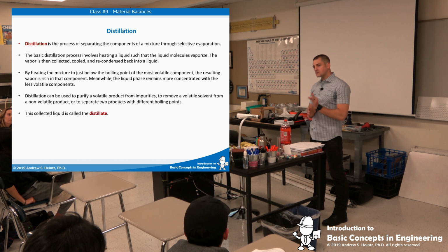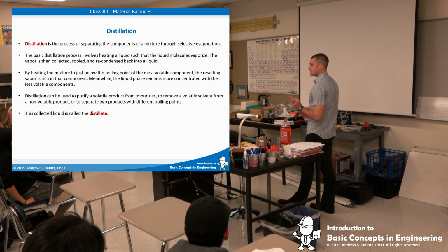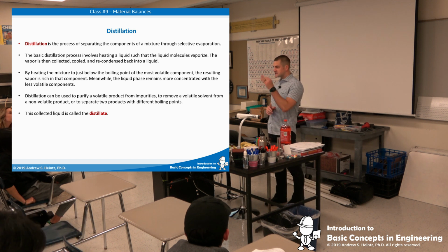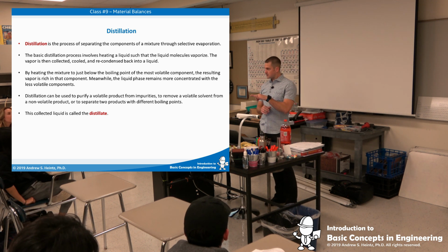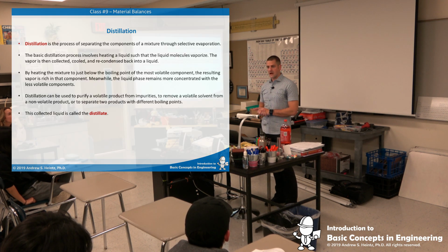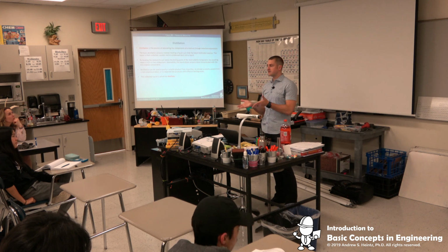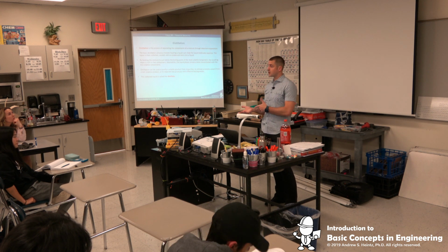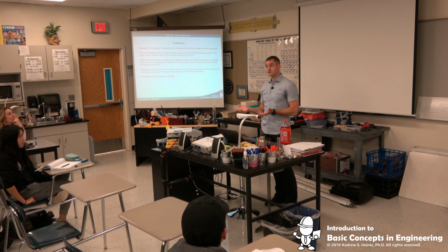And if we do it just right, if we heat the mixture to just the right temperature, which is just below the boiling point of the least volatile chemical, we can selectively get the majority of our product being one gas, right? Now, we all know that there's always some vapor pressure, so it's never going to be completely pure, which is why on some products you may see triple distilled, right? They're going to do it multiple times to try to do the process over and over again.